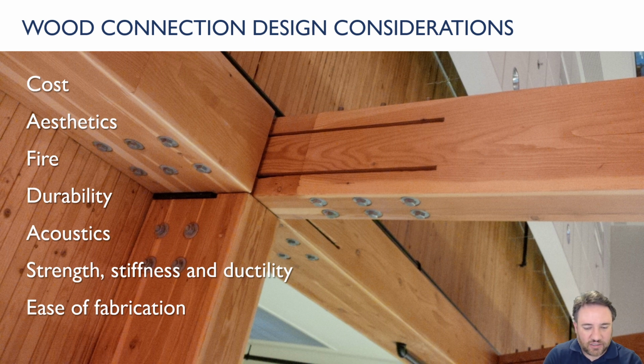Durability and acoustics, we're not going to cover a lot here, but of course strength, stiffness, and ductility are things that we're always interested in. And when we look at designing these timber connections using the clauses in the standard, these are going to be our primary considerations. But of course, ease of fabrication is maybe kind of a hidden consideration. As you get more experience doing wood designs, and seeing what happens when these members get fit up in practice, you probably get more experience in designing things that are easy to construct.